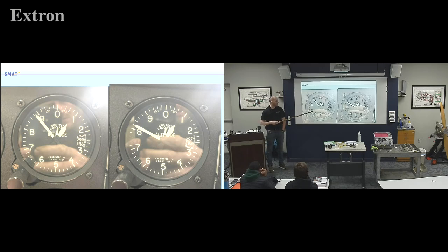So if I said, what is my true altitude this day, what number would you give me, Steven? Yeah, what number is that again? Oh, right one, I'm sorry. True altitude is above sea level, so it's the right one. I'm facing you. Sorry about that. Right one. So true altitude is above average sea level because I'm set up correctly. So if I'm standing here on the ground in Ionia, I'm truly 820 foot above sea level. So this one in Ionia set correctly.